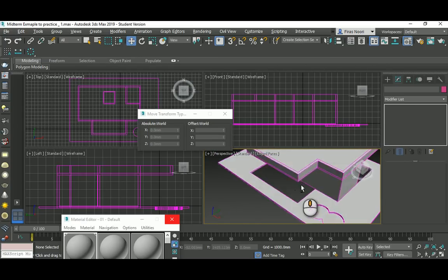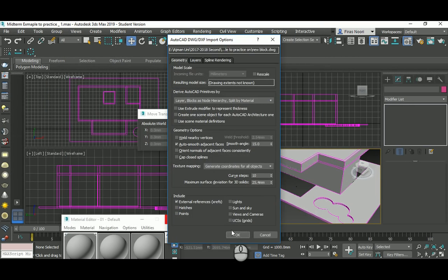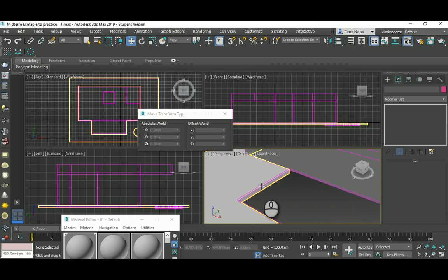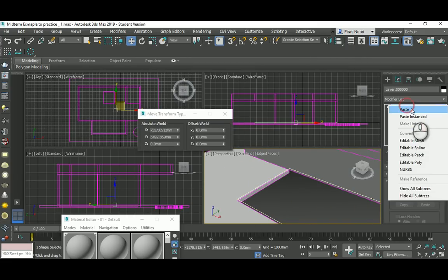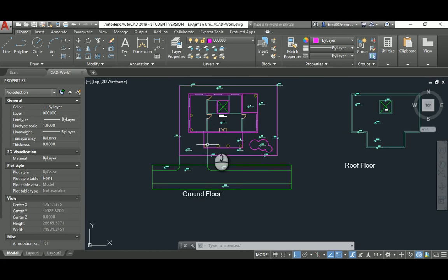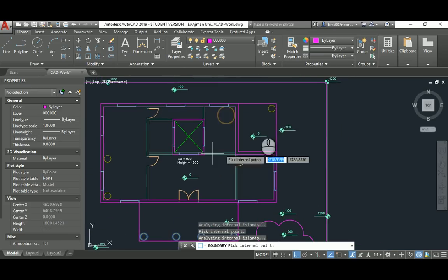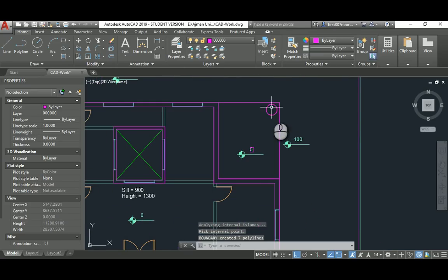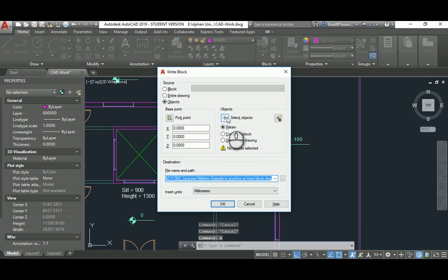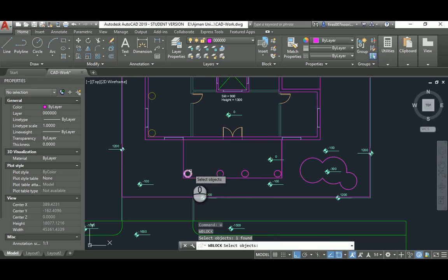I did, okay, alright. Should have done it when I did the ground floor. Anyway, too late, it's already on 0, so just paste and drop that, as you can see. Now boundary, and do the columns, just click them. I'm gonna ignore those inside the house, they make no sense. They were making more sense when this document had 2 or 3 levels. Should have deleted them anyway.